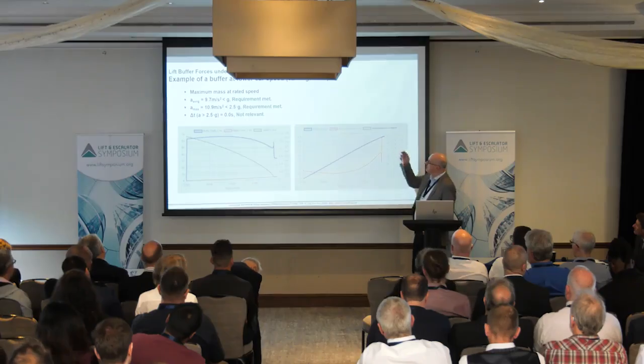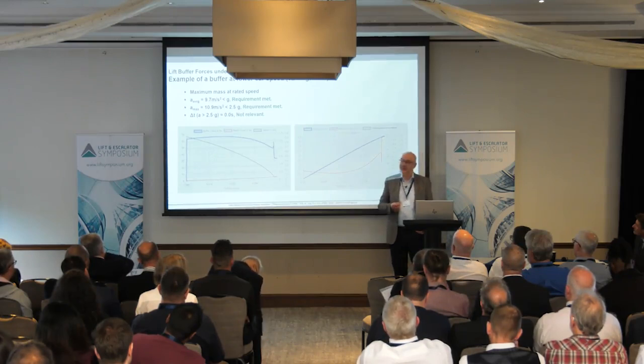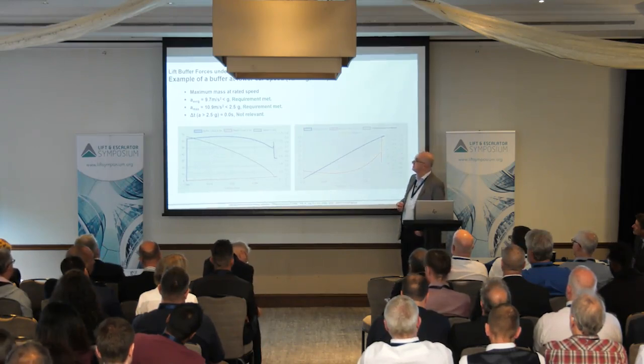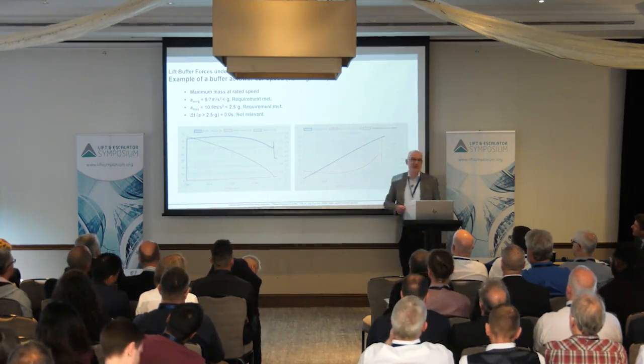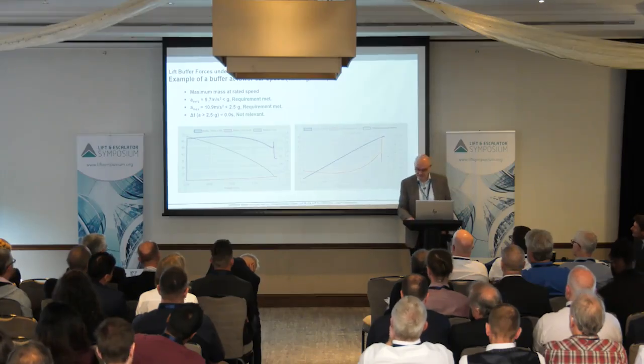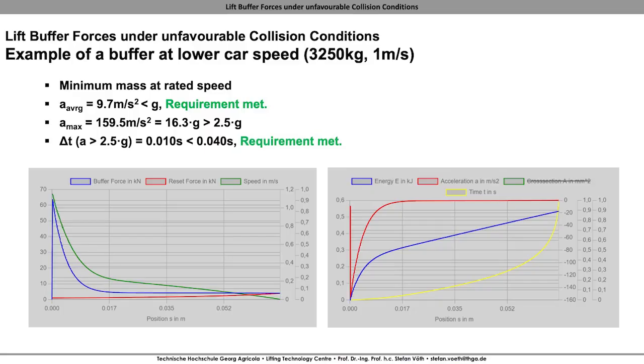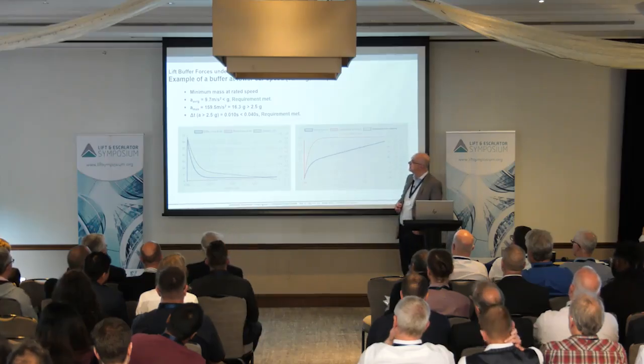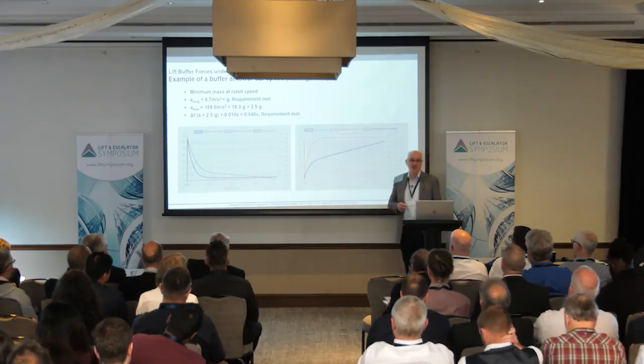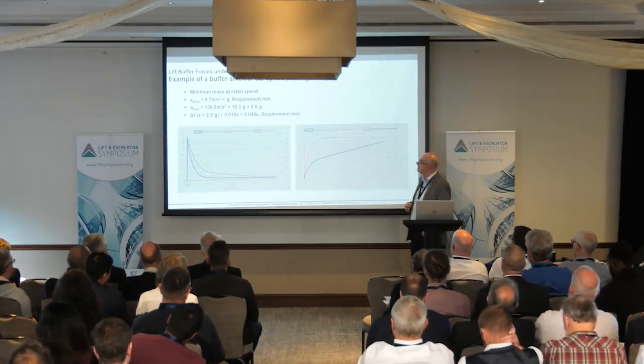If you look at the first case, the lift with maximum mass at rated speed, all the requirements are met. No problem. This is what you can expect. And if you go to the minimum mass of this lift, then also the average deceleration is met.